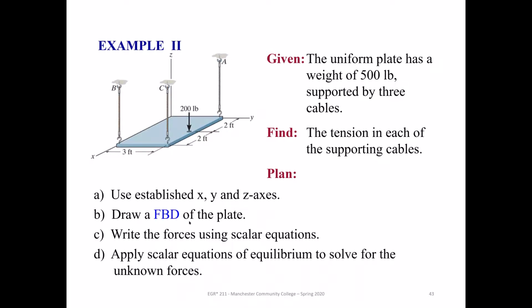Okay. So if you think about looking at the forces that are involved, what are you going to see? You're going to see force acting down. You're going to see a tension here, tension up, tension here. And then the moments, we'll take a look at those moment equations and how we're going to come up with the ones to solve it. All right. So right off the bat, we're trying to find the tensions. We have 3 unknowns, right? So we know we're going to need 3 independent equations to solve for those.